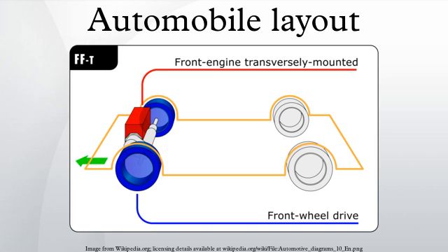Rear-biased weight distribution. When loaded, a rear-wheel drive car's center of gravity is shifted rearward when heavily loaded with passengers or cargo, which may cause unpredictable handling behavior at the hands of an inexperienced driver. It needs to be noted that rear-engine cars are, by their very nature, rear-weight biased.